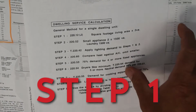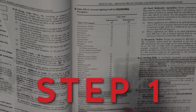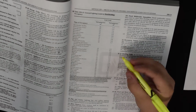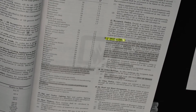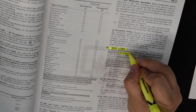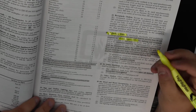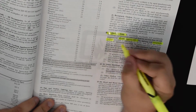Now we're going to go through the 9-step setup we talked about earlier. So we're going to go to 220.12J for step 1, and we're going to actually label it as step 1. Highlight the J, dwelling units. In 1 family, 2 family, and multifamily dwellings, the minimum load shall be not less than 3 volt amps per square foot. So highlight 3 volt amps per square foot. The lighting and receptacle outlets specified in 220.14J1, J2, and J3 are included in the minimum unit load. Just for understanding that, I would highlight receptacle outlets and then highlight included in the minimum unit load.